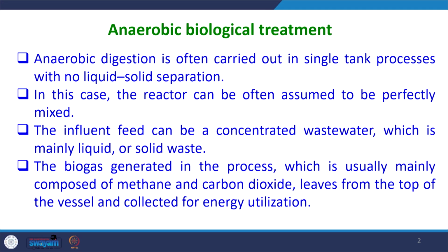Anaerobic biological treatment systems are often carried out in a single tank process with no liquid-solid separation. This is the fundamental difference, that they will generally be carried out in a single tank process. In this case, the reactor can often be assumed to be perfectly mixed. So, we assume CSTR type of systems. The influent feed can be concentrated wastewater, which may be liquid or a solid-based combination.